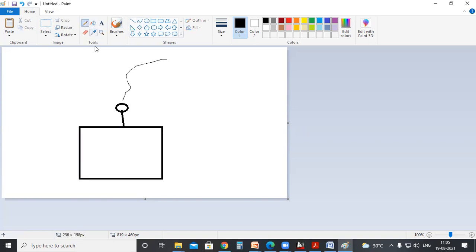From here, the down conductors are isolated using porcelain isolators. It is brought down, so you should not get any contact with the building. You have to make sure that it is going to the other side. This is a simple representation. I hope it is clear.